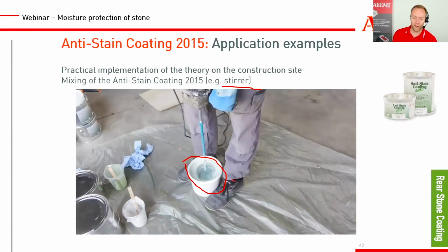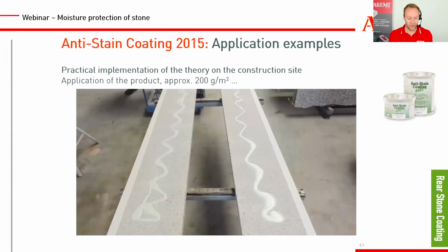So don't keep 3-4 liters mixed in a bucket, because then you don't have 20-30 minutes to work. Definitely not, because then the product already starts to react, gets heated up, and the curing gets accelerated. So you can mix 5 liters, but then start to spread it already on all surfaces like they did here. They mixed a good amount and then spread it on all available tiles.